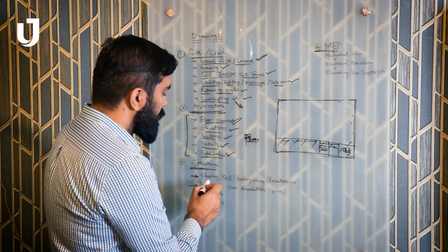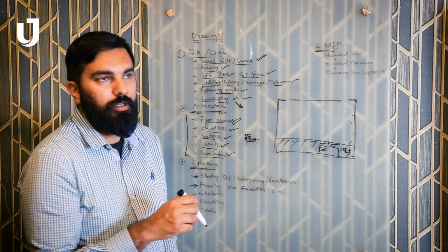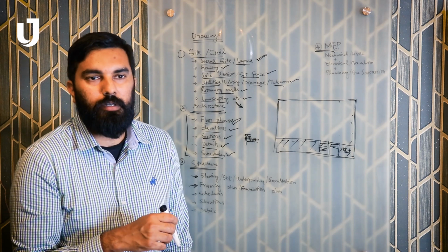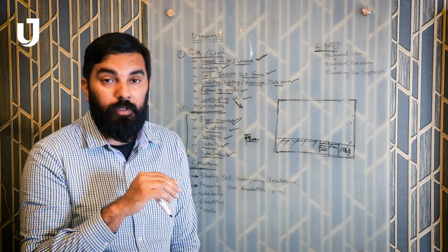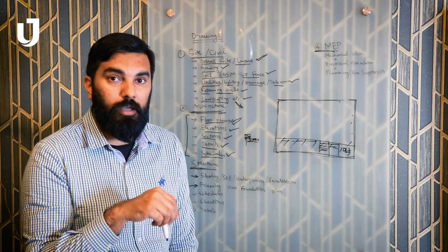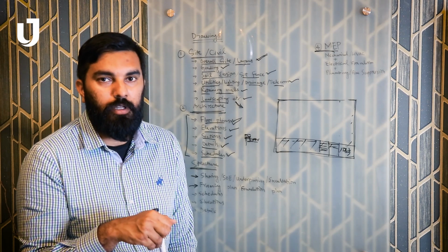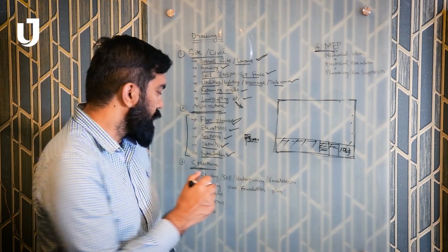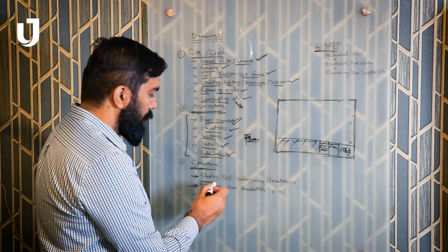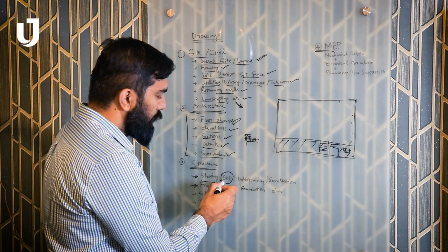sometimes in the buildings, there can be basements or there can be a cellar where we have to dig deep below the 5 feet. If you're going to be excavating more than 5 feet in the ground, you're going to have to provide the shoring. That's compulsory. So we'll be having the shoring plan. We call them SOE drawings.